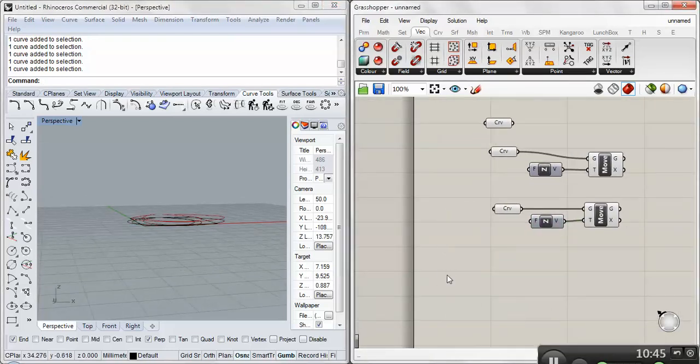And the slider, I'll show you again the notation for the shortcut for making that. So if you double click on the canvas, we want to have, let's say, minimum of 1, less than 10, less than 20. Alright, so that will create a slider with those presets. It'll be set to integer values, no decimals. Now we can connect that, move it up 20, copy, paste, and I'll set this one to 10.